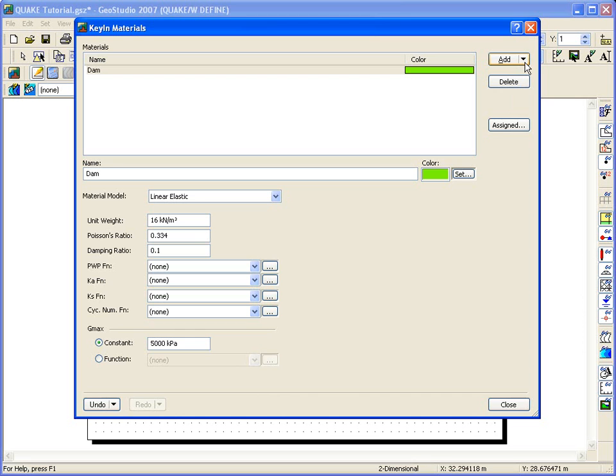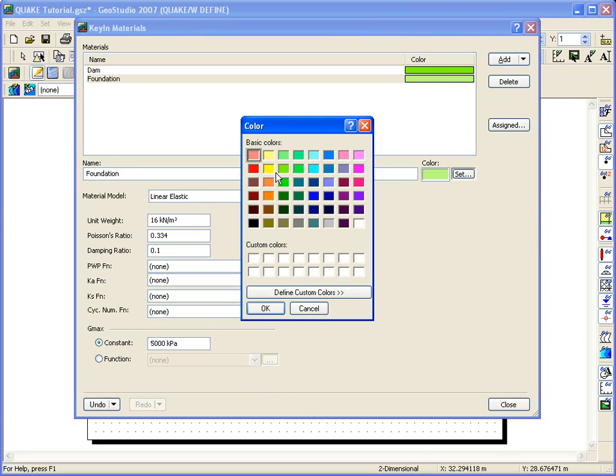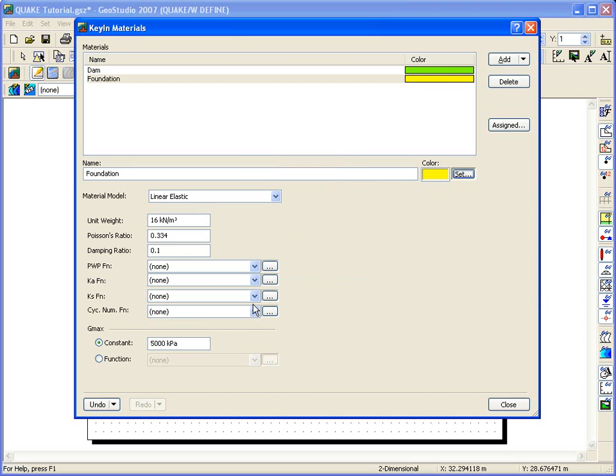To create the second material, you have options. You can either add or define a second material as we did the first, or you can clone an existing material since they're similar. Even though excess pore water pressures will not develop during the in-situ analysis, we want to model the generation of excess pore water pressures for the dynamic analysis.